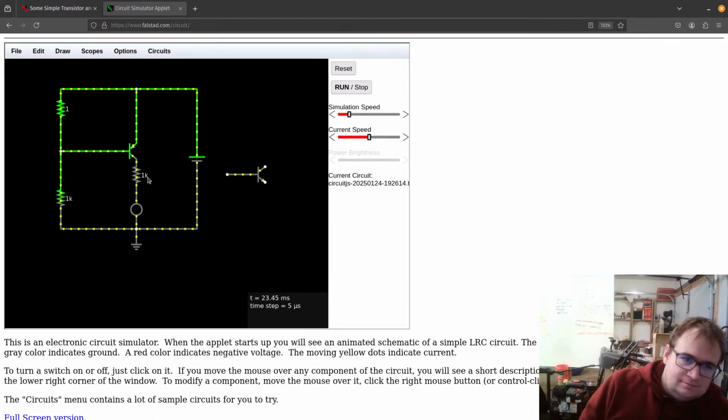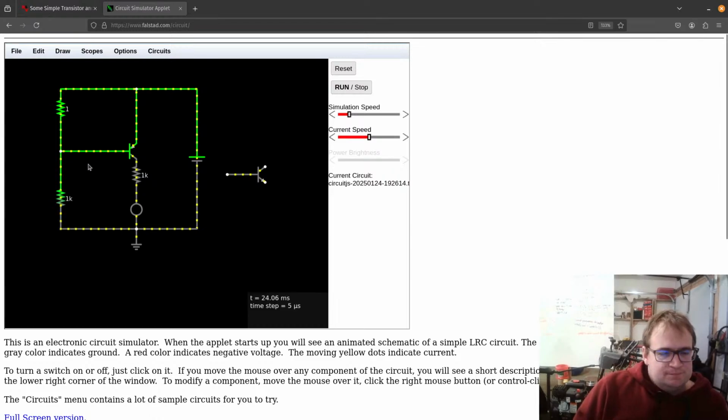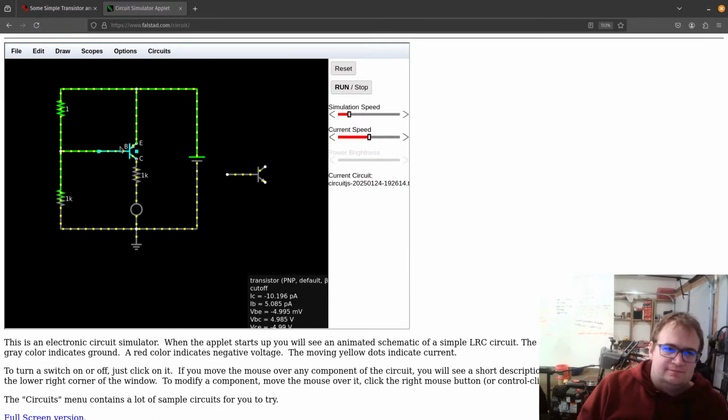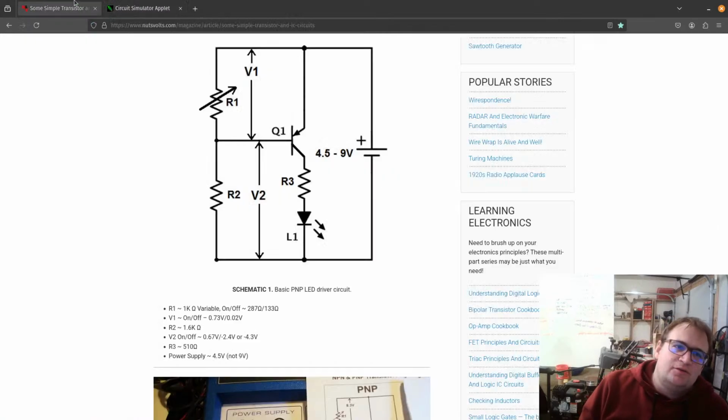So let's go back to thinking about currents with transistors. For transistors, it's all mostly determined via currents. So now this will drop 0.6 volts. I see, that's one diode drop. That's what's going on here.